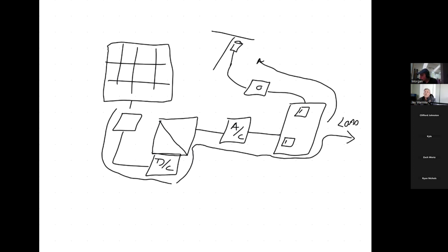And those smart inverters are supposed to be smart enough to say, okay, when I turn back on, I'm not just going to wait 5 minutes and then turn back on. I'm going to look at the grid, and if the grid cannot handle me turning back on, I'm not going to turn on until it's ready, until the grid can handle it. So these things have basically a little bit more flexibility, a little more internal intelligence.